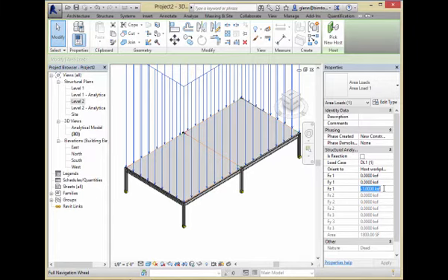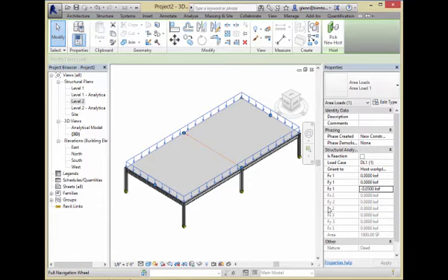So if I wanted that to be 50 pounds per square foot, it'd be 0.05. Okay, kips per square foot. That'll look a lot smaller. And is it a dead load or a live load? Let me make it a live load case.